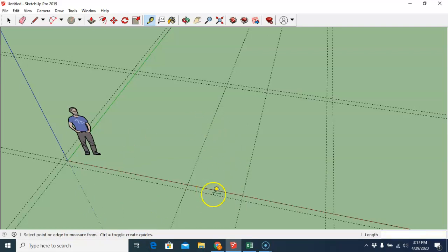And because I'm not going to be elevating this wall, I'm just going to draw in the rectangle. I'm going to draw my walls with a rectangle right here. So I start on the bottom corner and I drag all the way to the top corner. And that creates my rectangle. And now I can go ahead. I'm not doing this one either, and I do have a door on this wall. So I'm going to come back and take a measurement from here that is 5 feet or 60 inches. And then I have a 30-inch door, so I'm going to type in 30 inches.